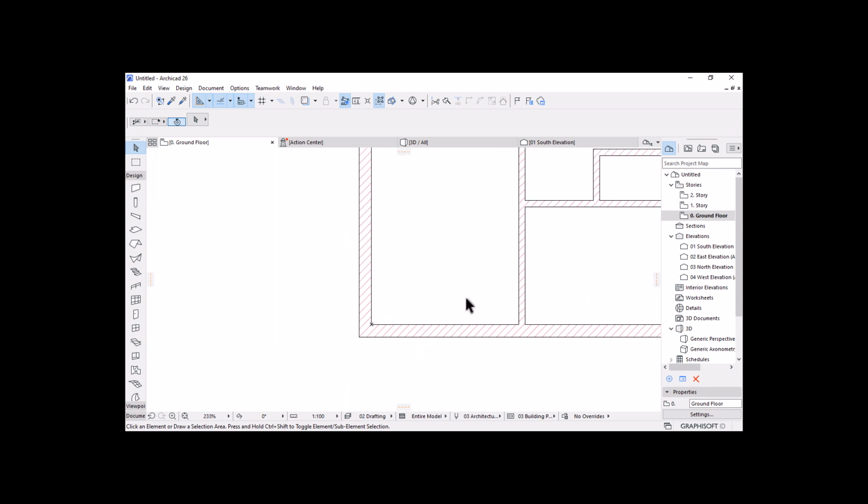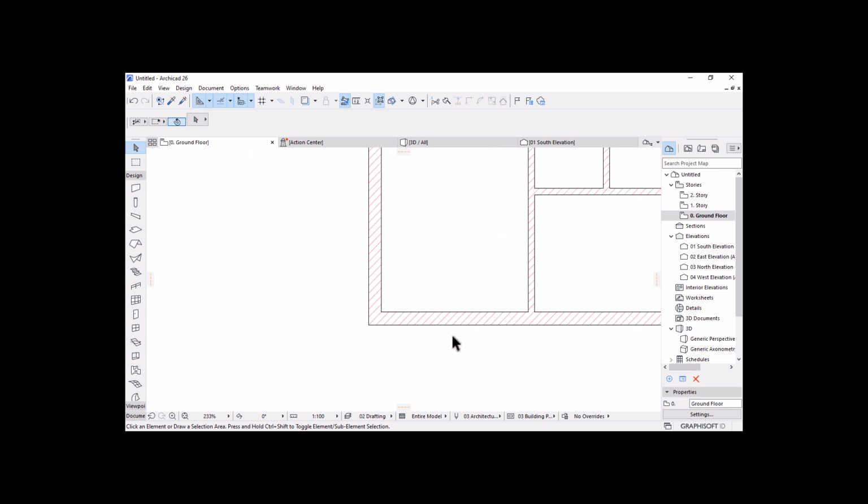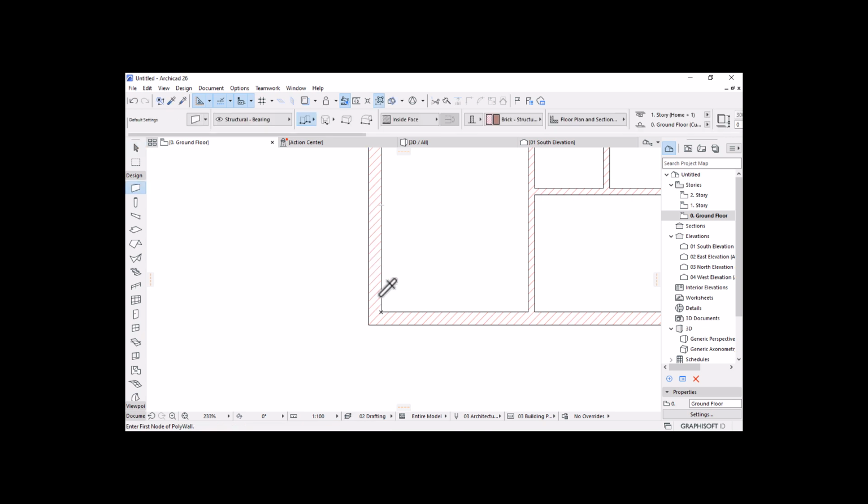And then we have the access to the main bedroom here. So this access is going to be at 2.2 from this side. So I'm going to pick this wall parameter by holding Alt, or you could come here and activate the pickup parameter tool, right? And then pick one of the exterior walls and hover on this corner like that, and then go all the way to this side and key in the distance at which this wall is going to be positioned, which is 2.2 or 2,200, and then hit enter. So now we have this position. I can now use it to place it here.